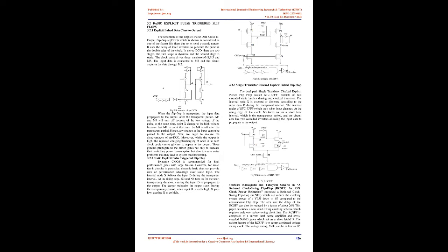Transistor count of the RCSFF is 20 including an inverter for generating D-bar, while that of the conventional F/F is 24. The area of the RCSFF is 16% smaller than the conventional F/F as seen from Fig 4 even when the well for the precharge PMOS is separated.